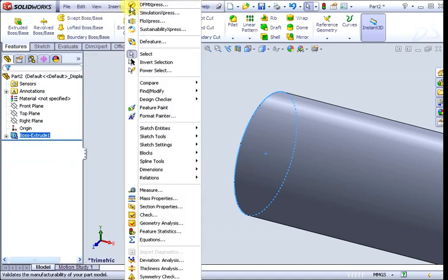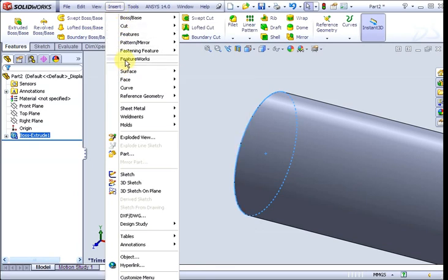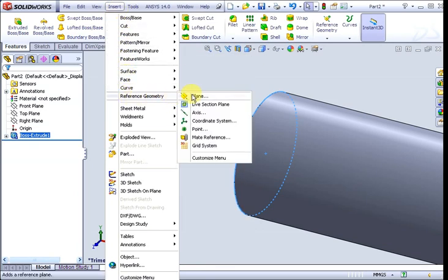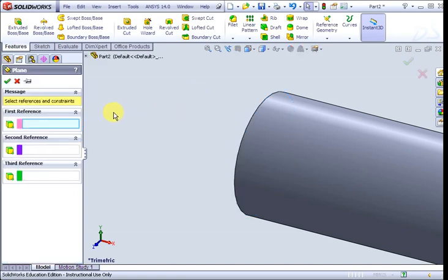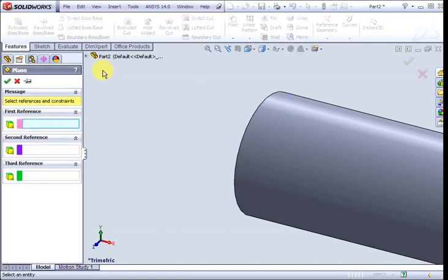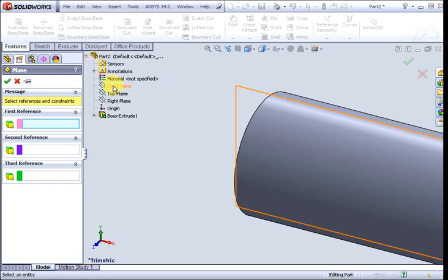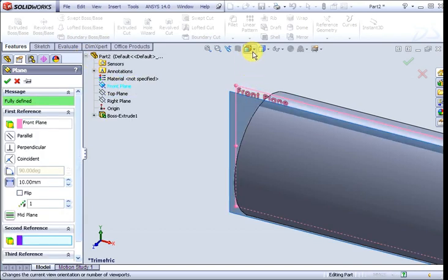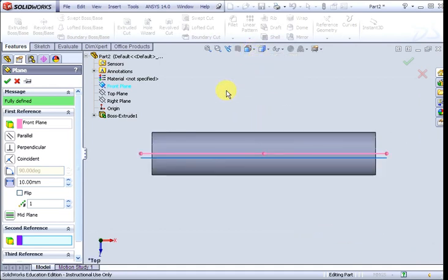So we first have to draw a reference geometry for the cross section. So we choose a plane. Okay, this plane, since we are drawing in x-axis, so this will be the front plane. We can see from top view. Okay, the plane will be the outer diameter of the swirler. So we have to move the plane far from the front plane. Okay, a bit, 55 mm. Okay, the plane is ready.